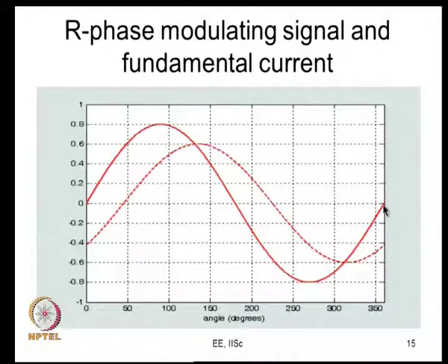Let us say that is being fed to a 3 phase linear load, so it draws a sinusoidal current. This represents only the fundamental component of the voltage. There are also harmonics. Those harmonic voltages would cause harmonic currents, but we assume that the load filters them out very effectively, since they are at high frequencies. So, it is only the fundamental current that is being considered here. Let us say this is the fundamental current. As I said, there could actually be a small ripple, but you can ignore that now.